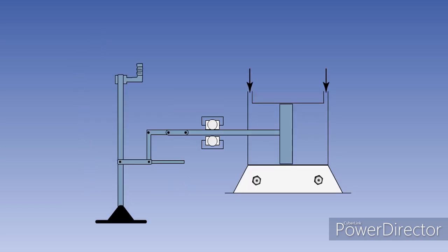Most modern aircraft have feel units fitted with devices known as Q-pots. These devices measure dynamic pressure in the same way that an airspeed indicator does. Q is the commonly used abbreviation for dynamic pressure. In the system shown here, static air pressure is felt on one side of a piston, with pitot pressure on the other. The piston, therefore, is feeling the difference between pitot and static pressure. The force pushing the piston to the right will therefore be proportional to airspeed, and thus proportional to the aerodynamic force being felt at the control surface.